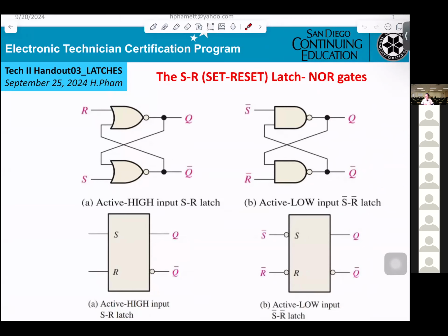If you get 2 unknowns, no way. You need to understand that when you run the test and it fails, either your program is not right, or your circuit board build is not right. With 2 unknowns, you cannot solve the problem.